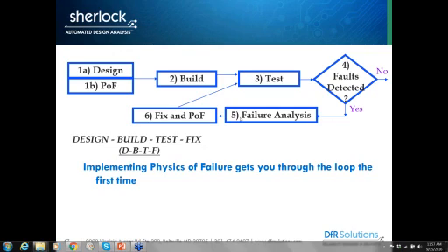If you have a net list, we know where all the leads are, so we can look at a distance check. But actual prediction of tin whiskers is very difficult, and I'm going to punt on that for now, because it's really a plating defect. You can make some types of predictions, but usually when something goes wrong with the plating solution, you get lots of whiskers.